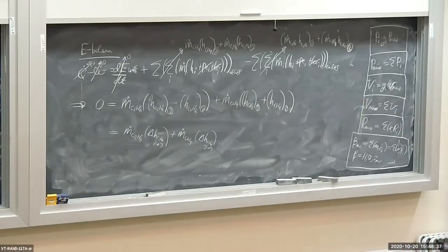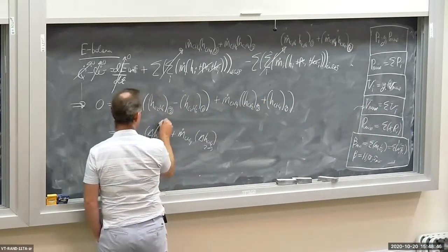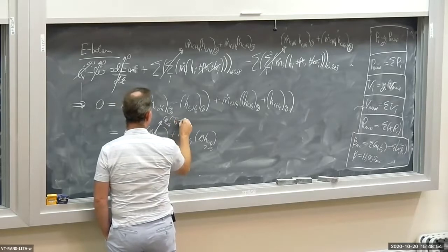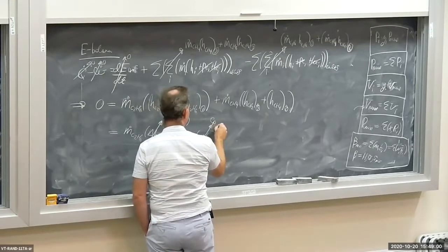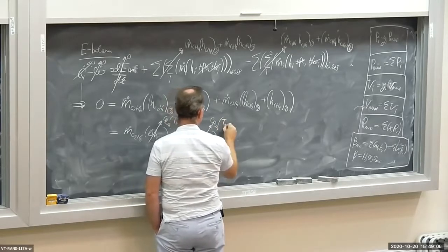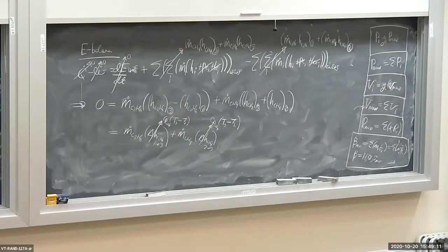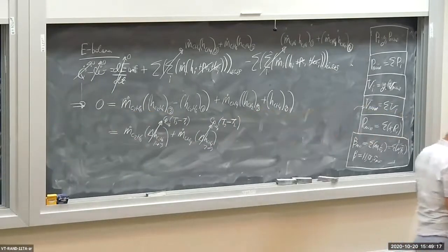Now, I'm assuming constant specific heat, so this delta H is equal to Cp delta T. So this is Cp of the C2H6 times temperature T3 minus T1. And this is Cp of the CH4 times T3 minus T2. Okay? T1 is the ethane inlet temperature, and T2 is the methane inlet temperature.